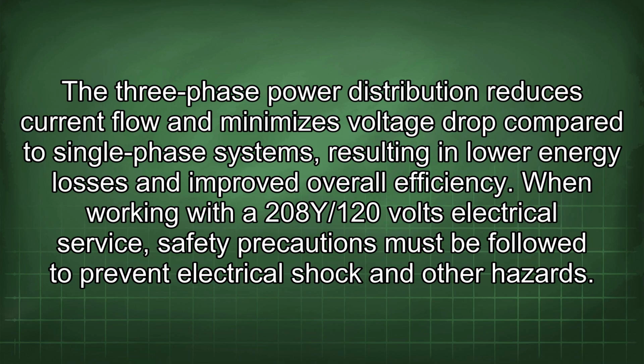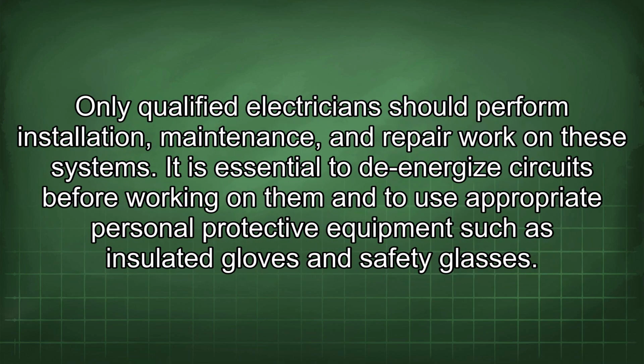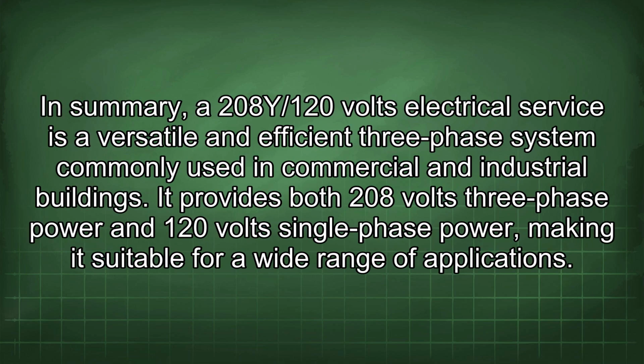When working with a 208Y/120 volts electrical service, safety precautions must be followed to prevent electrical shock and other hazards. Only qualified electricians should perform installation, maintenance, and repair work on these systems. It is essential to de-energize circuits before working on them and to use appropriate personal protective equipment such as insulated gloves and safety glasses.